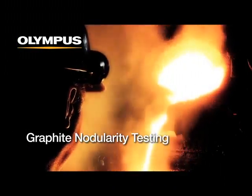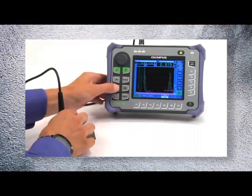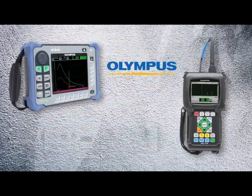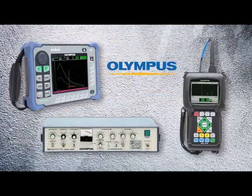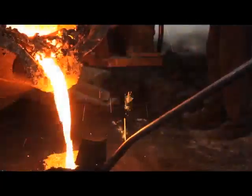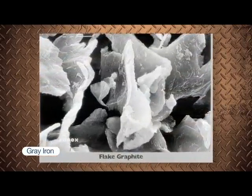Graphite nodularity testing in cast iron can be done with any instrument that is capable of measuring sound velocity. This includes an Olympus ultrasonic flaw detector, ultrasonic thickness gauge, or a pulser receiver system. The practice of adding graphite to cast iron is commonly used to enhance the material's mechanical properties. Gray iron is formed when added graphite arranges itself in the form of thin flakes. This results in a harder and more brittle iron.